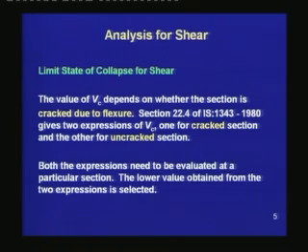The code says that we need to calculate the shear capacity of concrete from two expressions. One expression is given for the cracked section, the other expression is given for an uncracked section. Both the expressions need to be evaluated at a particular section. The lower value obtained from the two expressions is selected.